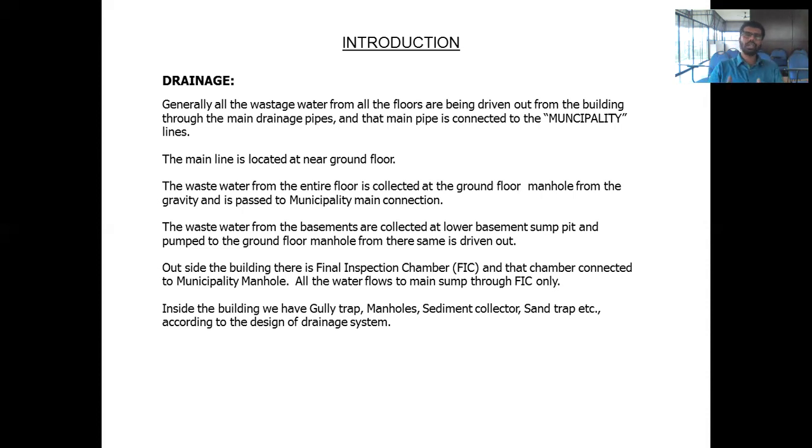If you are going to some Middle East countries, the sand will be deposited in the collection chamber. In that case, you should have a sand trap also, so that we can filter it, and then the water can be passed. So it depends upon the application. It won't always be used, but gully traps will be there.